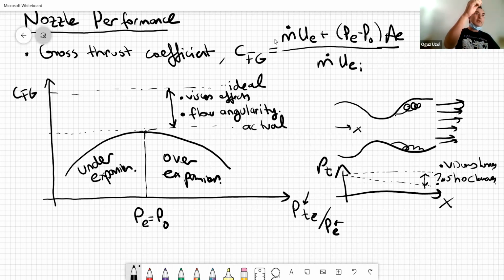As it moves up, it reaches a certain location where P is equal to P0 and then passes that. And when it reaches very high altitudes in the atmosphere and in space, the P exit is higher than P0. In space, P0 is actually 0, so it's always higher. So you see a very under expanded, very wide jet exiting the rocket engine nozzle. If you watch a few launch videos of any rocket system, old space shuttle videos or SpaceX videos, you can see that under and over expansion. We don't do anything about it because it's only an 8-minute flight, not a sustained hour-long flight.